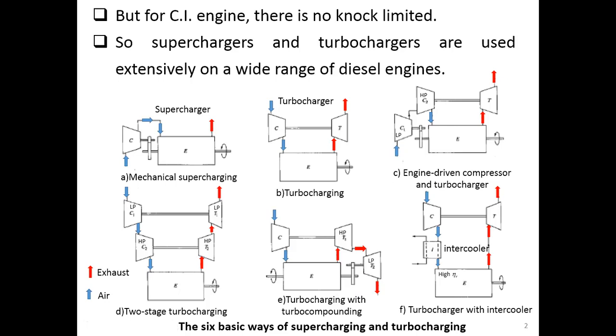So in this case, we use the exhaust not only to drive the high pressure turbine in order to deliver work to the compressor, but the exhaust that comes out can also deliver work for us to use, combining with the work from the engine through this low pressure turbine here.